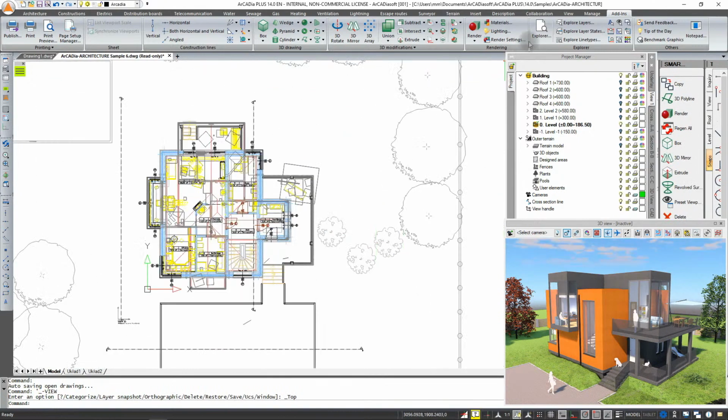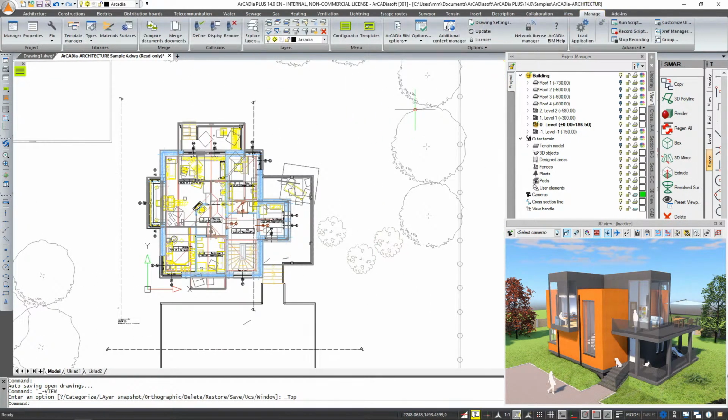Now, when it comes to the graphic module itself, there is a big difference. First, ArCADia and ArCADia Plus have all kinds of layer support, that is CAD elements that allow us to sort our project and set certain elements on layers. Thanks to this, we can block or unblock them. We can read Lisp applications, we can read XREFs. We can define commands by typing them, creating our own aliases and shortcuts.